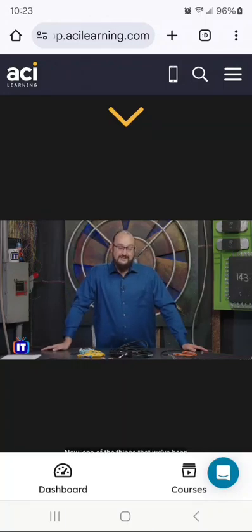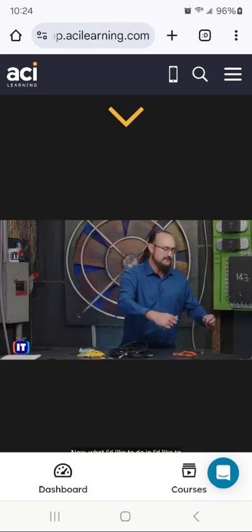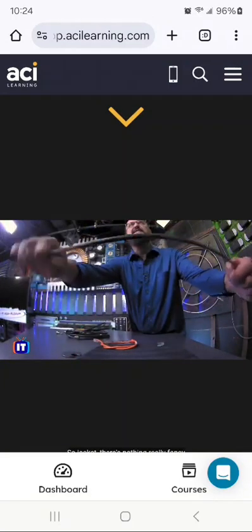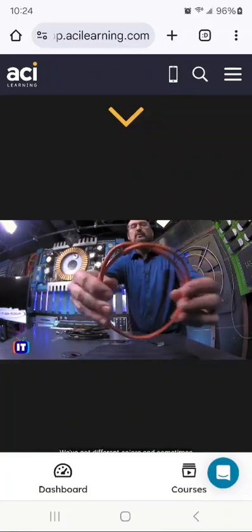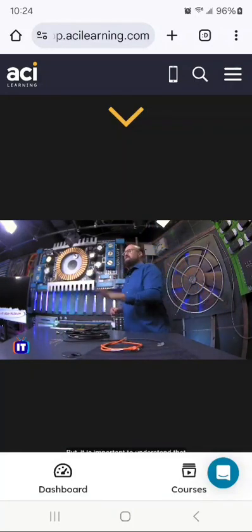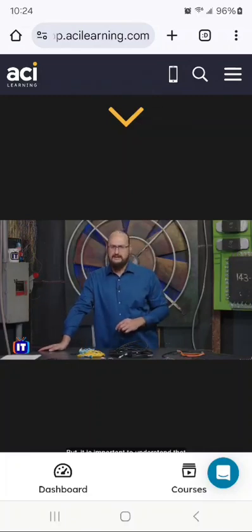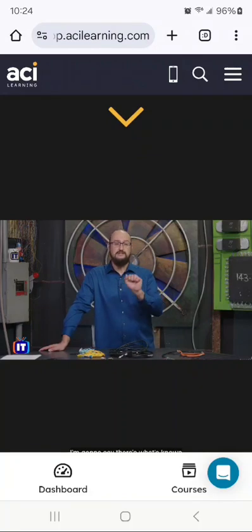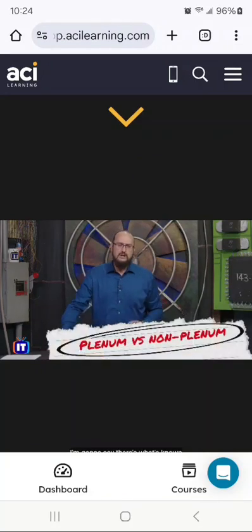Now, one of the things that we've been talking about is the internal makeup of the cable. We've talked about its conductors and what the twists do, how many conductors you have, as well as, like Ronnie mentioned, the termination of the cable. How do we put a connectivity jack on the end of it? Now, what I'd like to do is focus in, everyone here, on the jacketing itself. So jacketing, there's nothing really fancy about it, it doesn't really look like much. We've got different colors, sometimes for different specifications. But it is important to understand that there are two different types of jacketing. There's what is known as PVC jacketing, and there's what's known as plenum. I'm going to say there's what's known as plenum and non-plenum, all right?